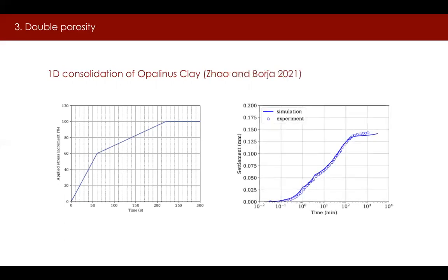The figure on the right shows the settlement time history for one of the many stages of loading, with a simulated response matching the experimental data points quite well. Note that the settlement time response does not flatten out, but instead continues beyond the primary compression curve.